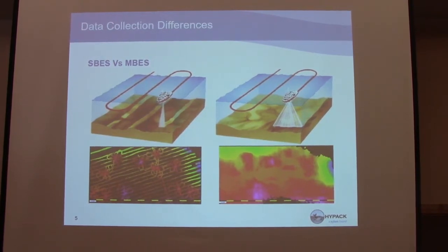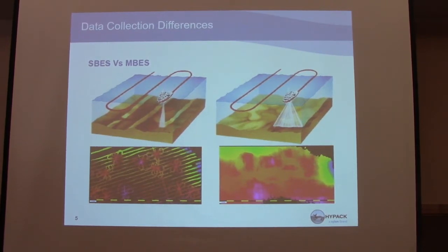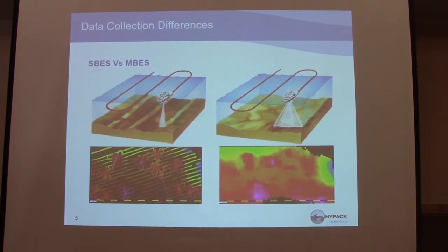A lot of berths, when you're up against a berth and running parallel with it, you're in 30 feet of water and you can go out to 60. I'm new to this multi-beam. Right, so the program will see that the swath has measured a 60-foot depth, so it will make that line farther apart in that one particular area, because it's a multi-segmented line. Now it's going to separate the lines a little bit more because you're getting a wider swath width in deeper water.